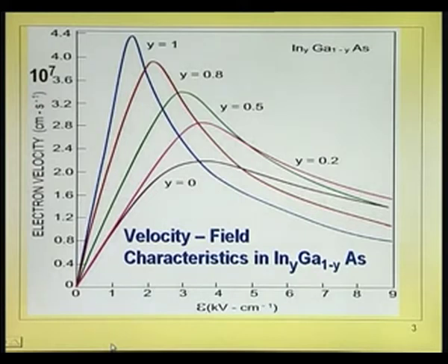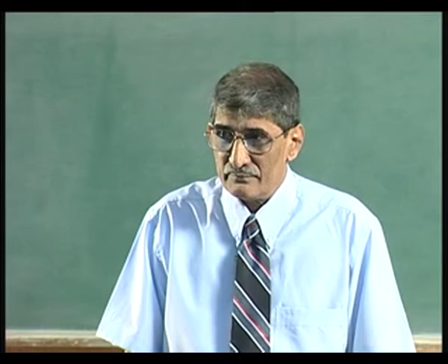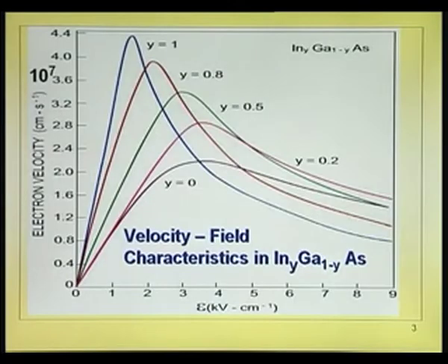So, the key thing now is the lattice match between gallium arsenide and indium arsenide, or gallium arsenide and indium gallium arsenide. The whole problem is indium has a tetrahedral radius of 1.44 angstroms, gallium is something like 1.26 angstroms. That mismatch brings in lattice mismatch. So, you are not able to grow gallium indium arsenide on gallium arsenide without defects generated, but we will see later today if possible that such a thing also is possible if you take certain things into account. Okay. We will go back to that. Right now our understanding is you need really lattice matching, you definitely need that.